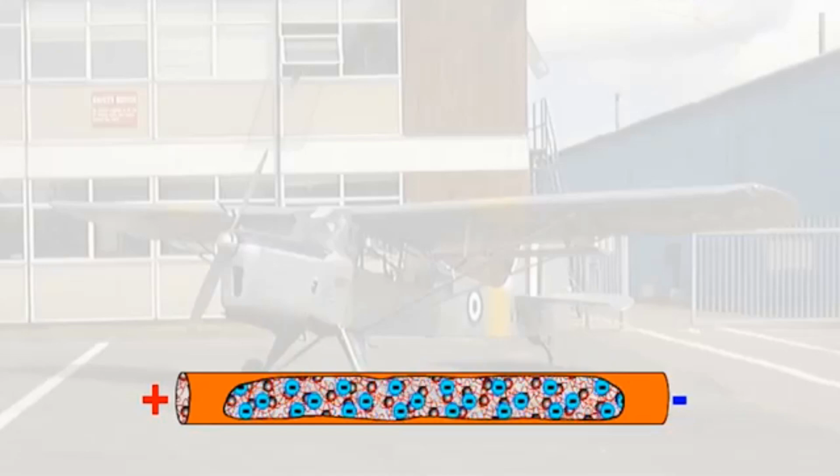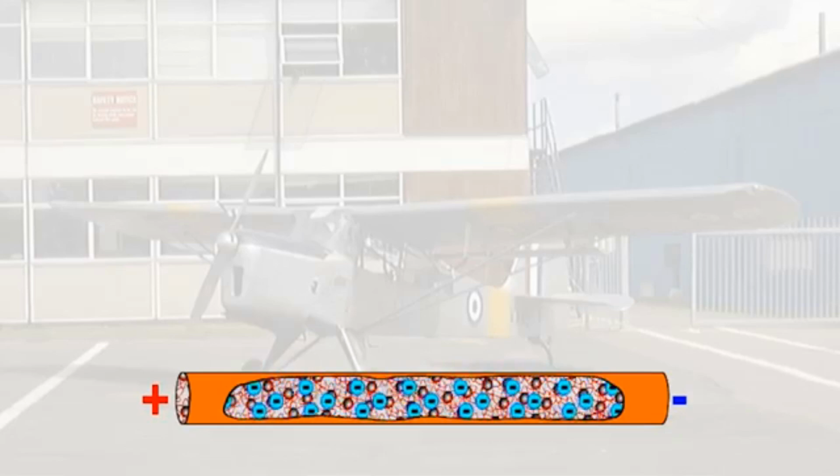Most light aircraft use a direct current, or DC supply, to drive the electrical services. The term direct current implies that the electrons which make up the flow of current are travelling in one direction only. Convention states that the electrons flow from a positive source to a negative. Alternating current, on the other hand, has the electrons in the circuit moving backwards and forwards about a mean point.